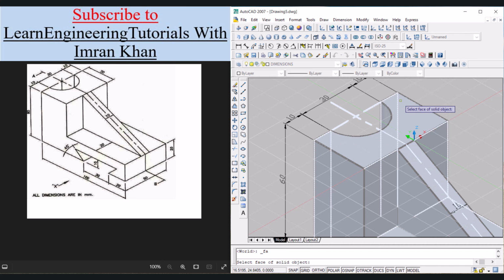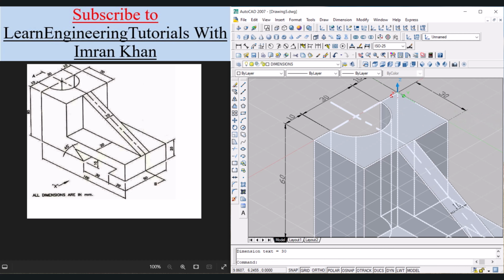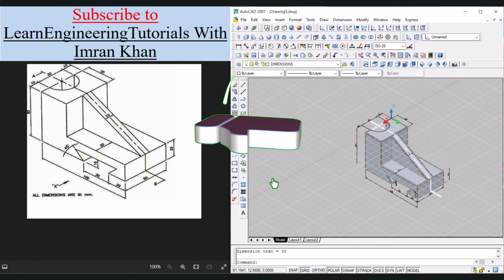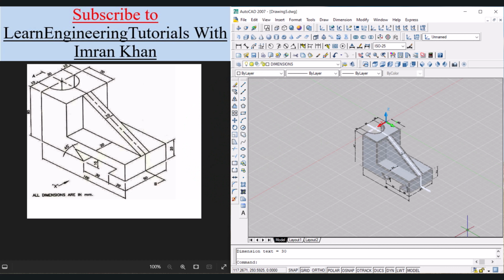Click on face UCS and click over here, click accept. Click on linear, click on this endpoint, click on this endpoint, move the cursor away and click. So the UCS was placed correctly. Now the dimensions are complete. All we have to do is to add the text and show different directions.